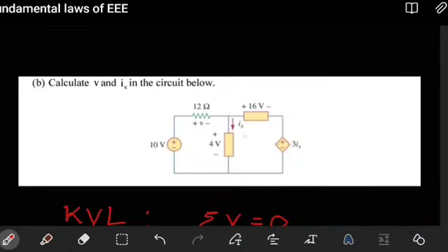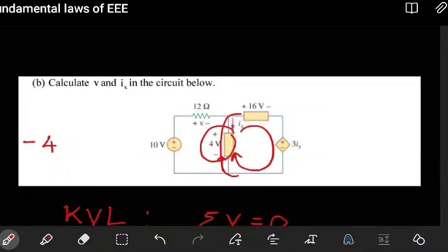To find Ix, we're now going to use Kirchhoff's voltage law, but on this side. The same concept applies. When we start, we find negative first of this circuit element down here, so we write minus first. And the value there, again, is only a voltage, so this will be minus 4. When we continue, we now find the 16 volt drop across that element. This time we find positive first, so we have plus the 16. That's a voltage value, so we go with the voltage.